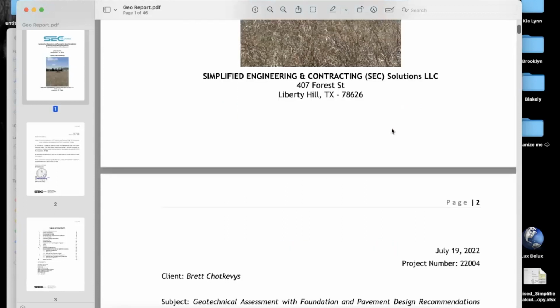You think you're going to build a concrete slab, right? You're going to have these concrete beams that go around the outside, the perimeter beam, and the beams through the middle. And it's pretty common, okay, they're 12 inches wide, 24 inches deep. But mine, he has them spec'd at 54 inches, like crazy deep. And he'll take it into account based on the shape of your building, how big it is. And again, these assisted livings are super long. If it was just a 3,000 square foot square, no big deal, it's all square, but we're talking L's and like 150 feet long.